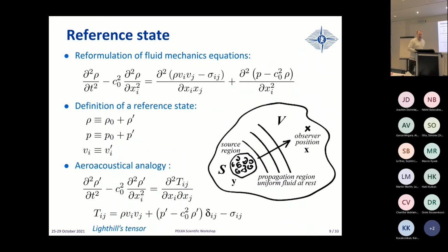And that's how eventually you have shaped up your aeroacoustical analogy. So you have the left-hand side that is now the real wave propagation operator you were looking for, and everything that has been put on the right-hand side becomes de facto the equivalent sources for your new problem, where the medium is uniform and at rest. Okay, so this is the equivalent sources that are producing the acoustic field that you measure, and it contains a number of terms